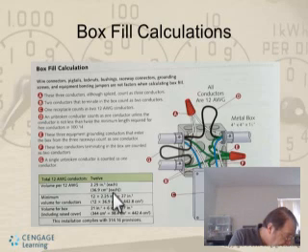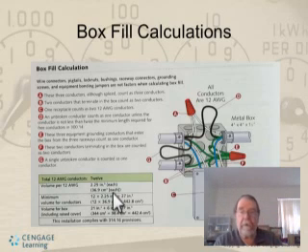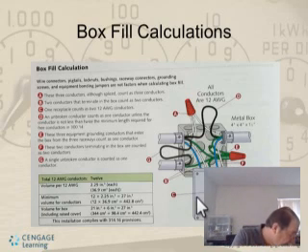The minimum volume for conductors in the box is bigger because the cover has 6 cubic inches, so that's why you get a little bit more room in here for conductors. If you look on the label on this box, there's a label that says 6. If you look in your book, it'll tell you that you can add that together and come up with total volume.